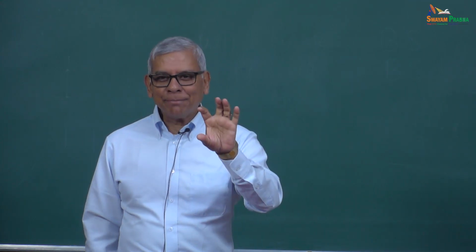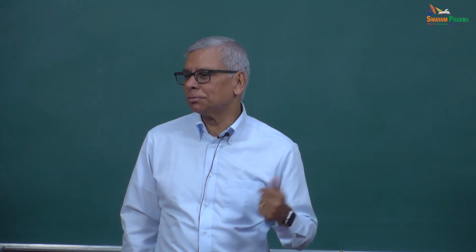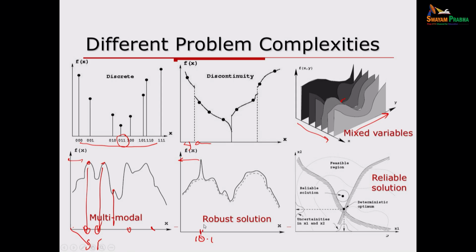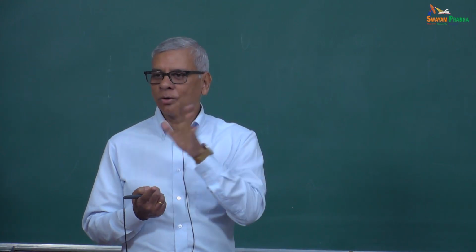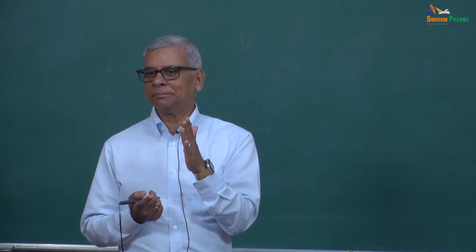So you set up 10 mm dia, when you do it, it may be 9.99 to 10.02. So you are here or here, and look at what happens. The function value drops suddenly. If only you can adhere to 10, you get this highest optimal value. Otherwise, you are bad. So these are called isolated maxima or minima.